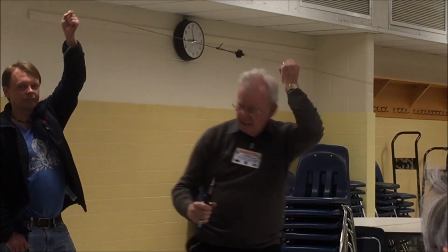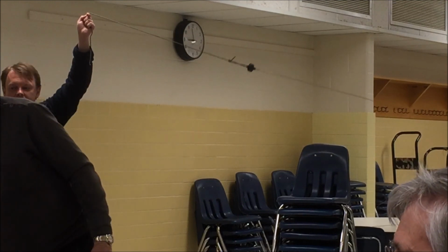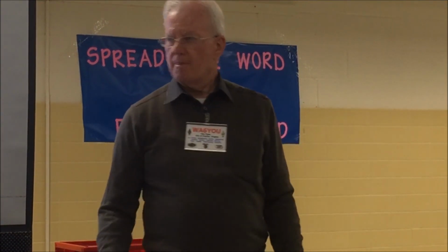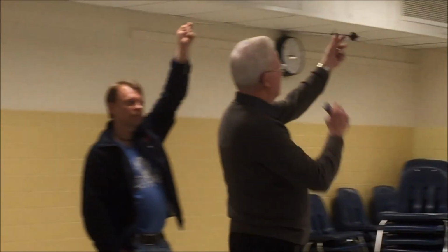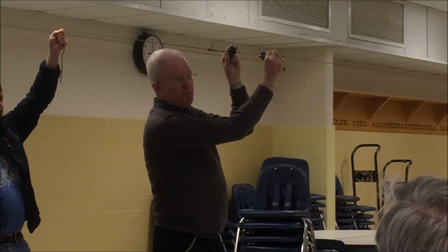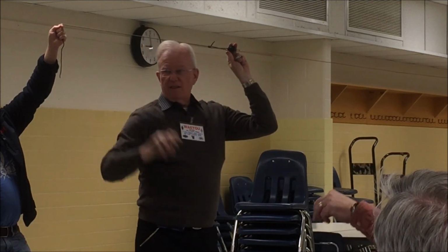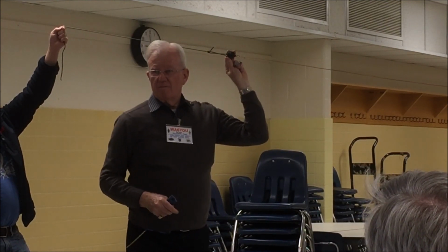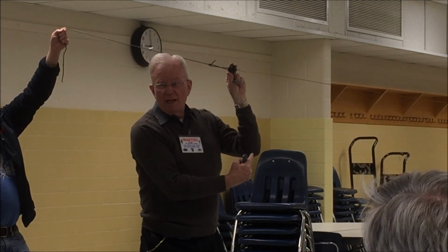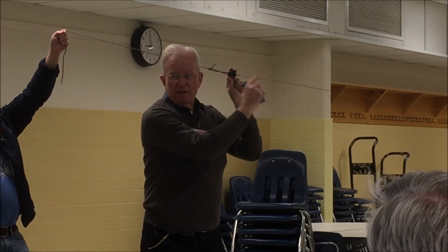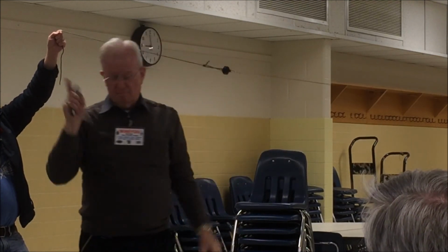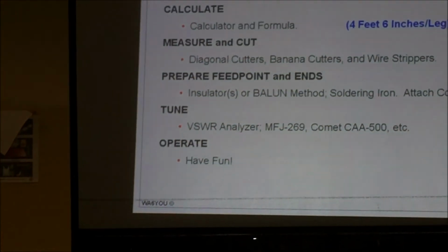So, Ron, when you're in the process of getting it the right length and you have excess wire on the end, does that have any effect? I like to twist it and put it down here. It has no effect at all. Just don't let it hang down. Make sure it's linear on this, around here, okay? You betcha, because that does have quite an effect.